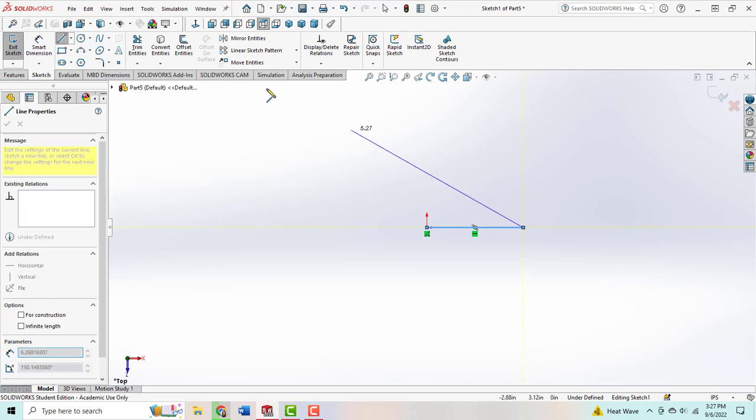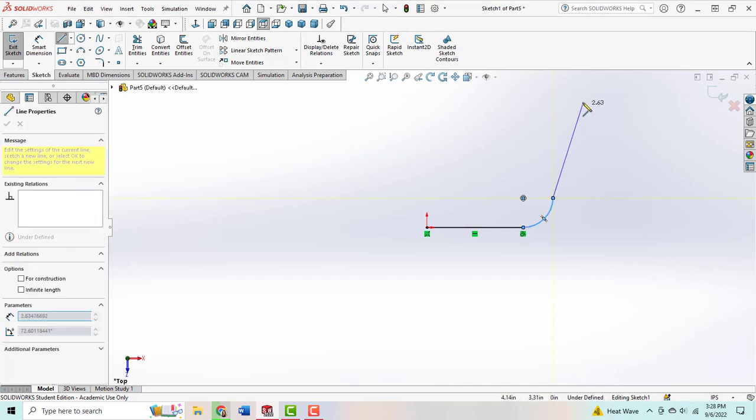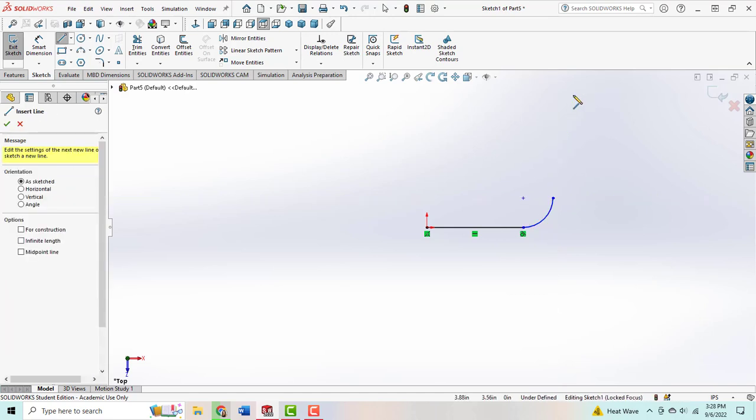Now, instead of coming up here and selecting the arc sketch tool, because I am just in that straight line, one shorthand is you can bring the mouse back to that endpoint and then it will give you a tangent arc. So this only works with tangent arcs, so it's going to be great for this application. Once I hit the endpoint down, it goes back to being a straight line.